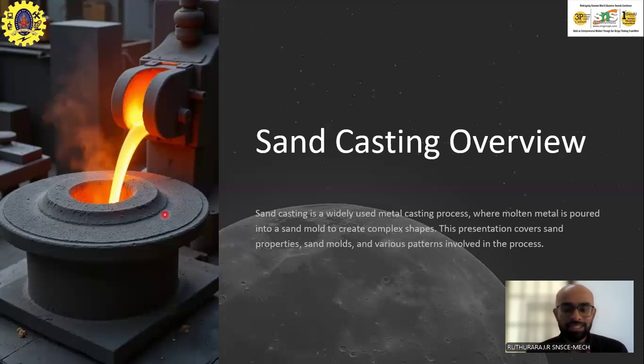Hence, metal casting means that you are creating the shape of an object with the help of an impression. You'll have a die or a pattern which will be the exact replica of the component which we are making. That die will be used to make an impression on sand in case of sand casting, or other materials in case of special casting, which we will see in the subsequent lectures. Once the impression is made on the sand, molten metal will be poured over it, and the required size and shape of the component will be obtained. So this is the overview of the casting process.